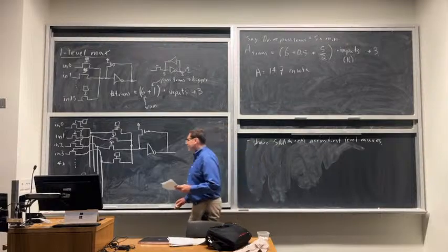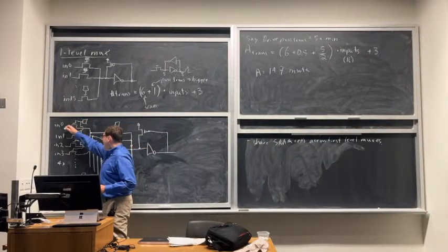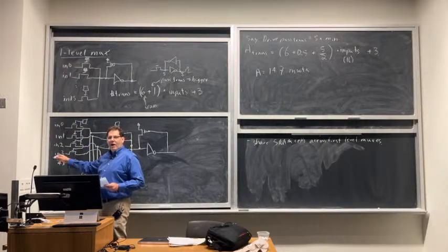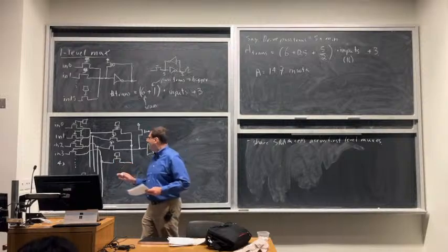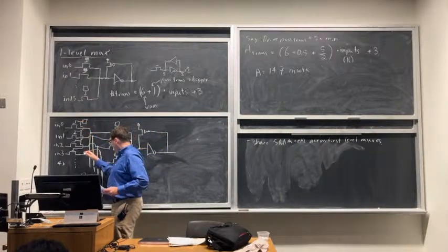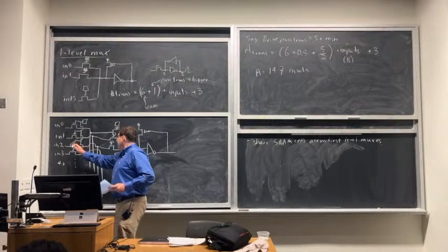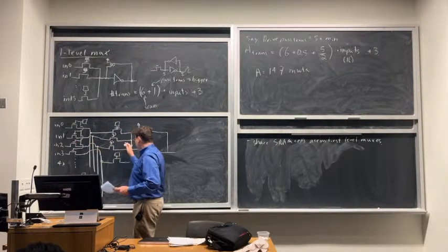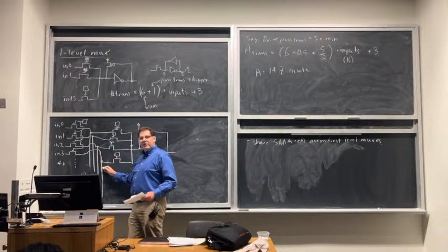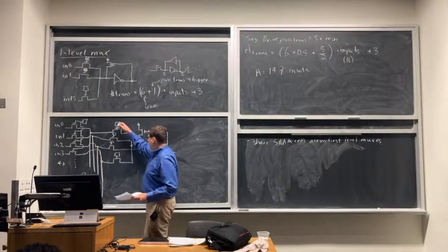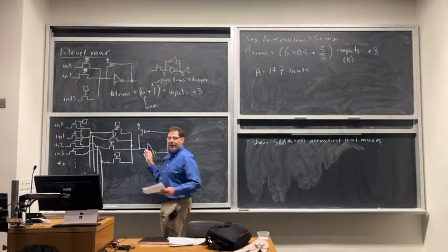So it's leveraging the fact that, by programming this, what the CAD tool does is, if I want any one of these 4 routing wires to make it to the output, that's what the CAD tool says I should connect, then it'll program a 1 in here and the other 3 SRAM cells will have zeros. That actually means 4 signal paths are activated. So I get 4 signals making it to the second level. And then the CAD tool programs one of these 4 with a 1 and the others with 0 to make sure it gets the right value to the output.